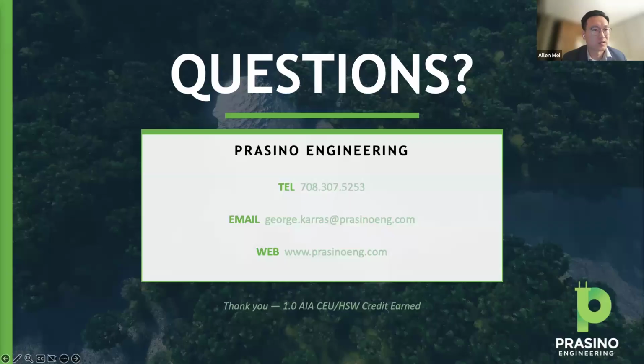You basically kind of seal up each apartment. You sample them, typically 20% of those units. Generally, the blower door testing follows ASTM approach, and ASTM is a little blurry on specifics. My recommendation is work with the AHJ. Have the AHJ tell you, hey, how do they want to see it? Because technically, if you have big enough equipment, you can test the building instead of going to each apartment. So I would say work with the AHJ, ask for specifics, because at the end of the day, the building officials give you the certificate of occupancy. If they wanted to see certain things, sure.